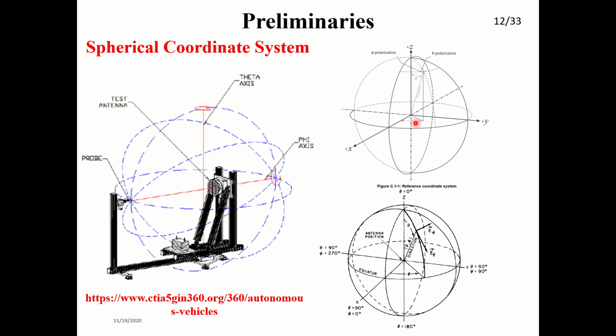What I want to say is that, for example, your antenna is kept at the origin of the spherical coordinate system, and you are measuring at these points, like on a sphere. You consider that inside the sphere, at the origin, the UE or device is placed, and you are measuring at these spherical radial points and capturing the different parameters. In conventional measurement we will not take all the points of the whole sphere. We will take two principal plane cuts.